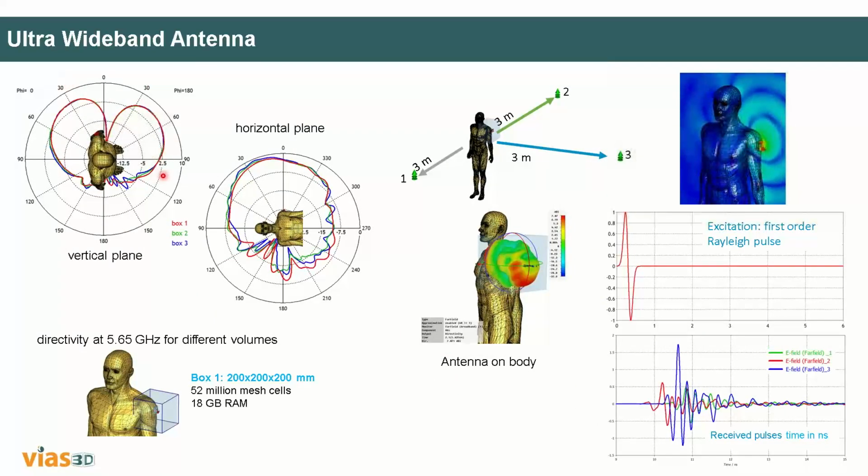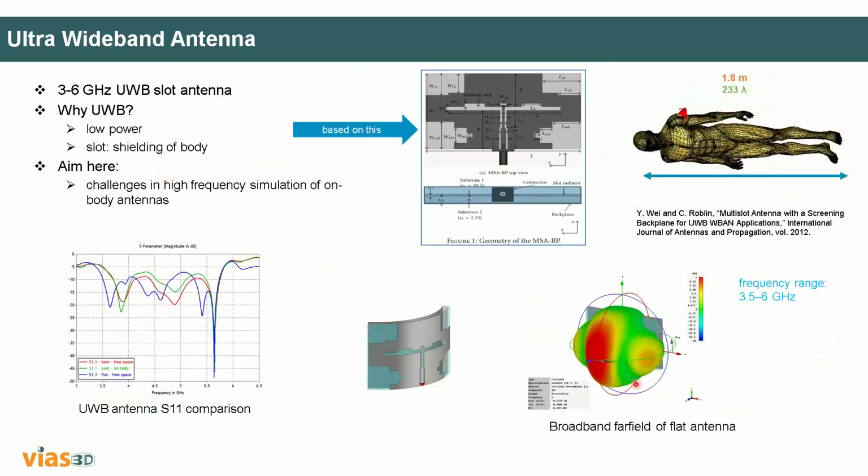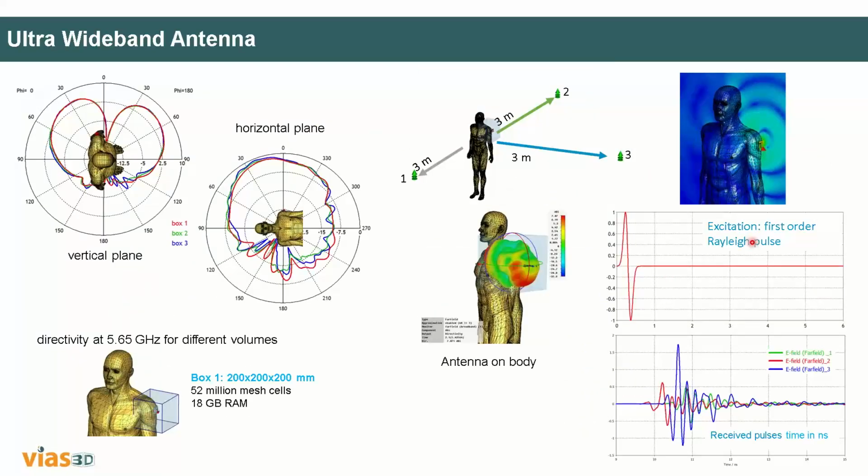So you have the radiation pattern. I just want to tell you that this is a radiation pattern without placing it over the structure. When you place that antenna over the structure, you can see there is a perturbation here. Obviously that will happen when your antenna is actually going to operate along with the platform. Because of the platform, it will have changes in the pattern. And you can see the radiation pattern over here.